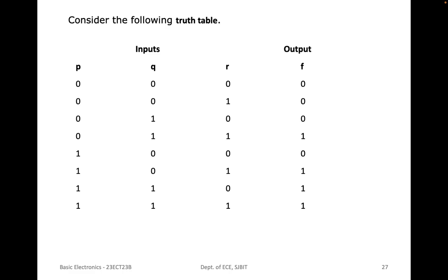The Boolean function f is the dual of the Boolean function of minterms, just like the Boolean function for sum of products is the dual of the Boolean function for the product of sums. Therefore, both canonical SOP and canonical POS forms are dual to each other. Functionally, these two forms are the same. Based on the requirement, we can use one of these two forms.